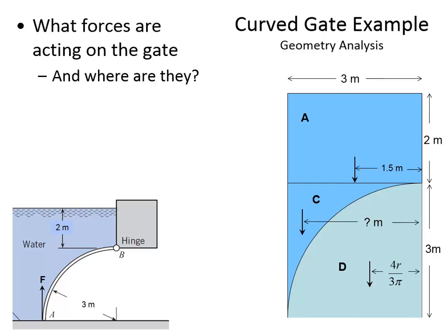We've got over here the force due to element C, as we called it, pushing the gate closed. And then we also had this horizontal force that we just calculated. We'll call that the F sub H, the horizontal force. And all three of these are trying to push the gate closed, or turn the gate counterclockwise, whereas when we want to start opening the gate, we're going to have it rotate clockwise.